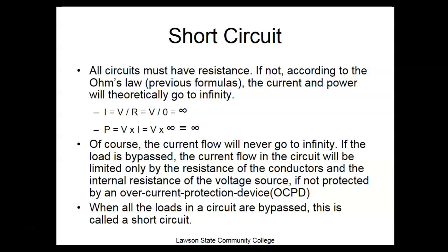These are protected by overcurrent protection devices, and fuses are used a lot. The big advantage of fuses is that they're a lot cheaper, but they destroy themselves. With overcurrent protection devices like circuit breakers, we can reset them. If they sense an overload on your conductors, they'll trip or pop or whatever you want to call it, and we have the ability to reset it.